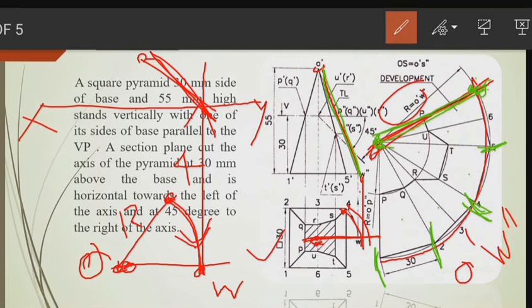Okay, then draw an arc like this, and then we measure the length 30, and then from the point, first we put a point here and the sharp edge of the compass here, and then make an arc of 30 here, and then again 30 arc, and then again, and then again, and the final last point we will join from the O. I will get this development. Okay, we will get the development.